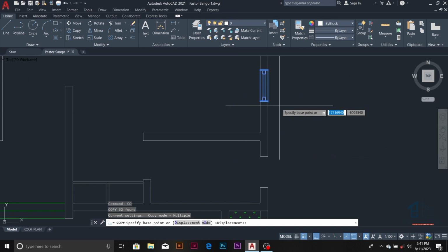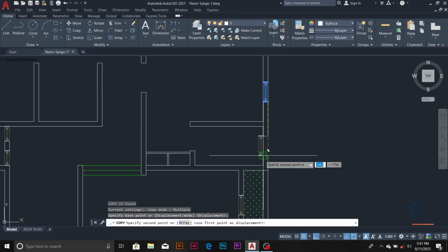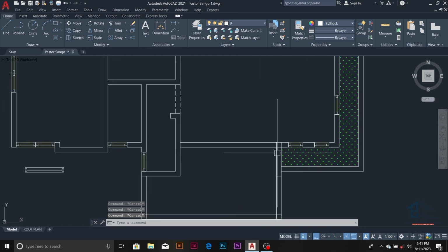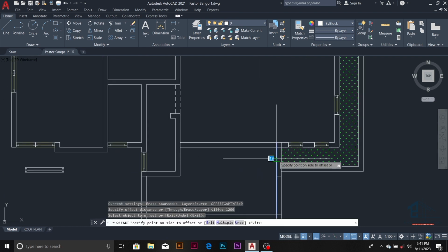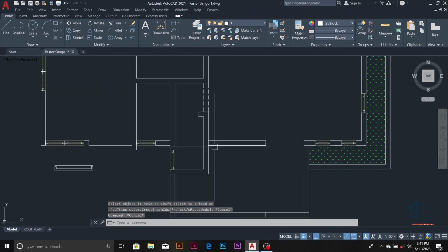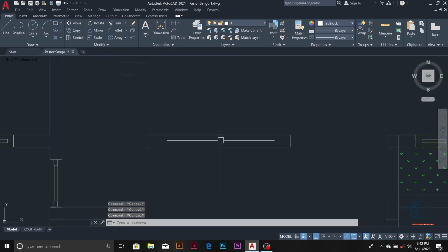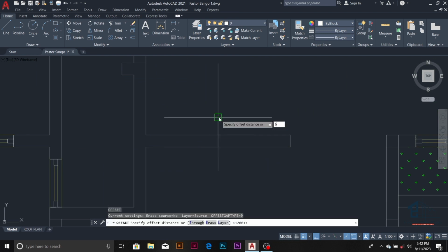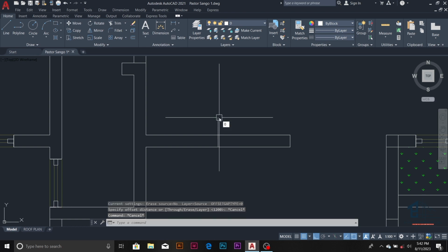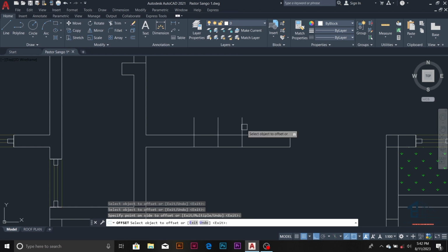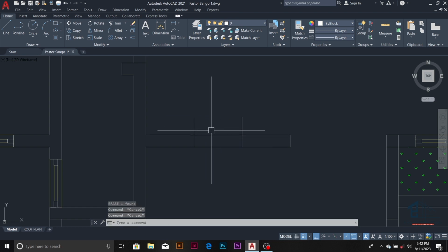So you will copy. So there's door here, offset 1.2, I'm using 1.2 door. Trim it here. Trim. And just put small door window here, offset 300. Trim it. CR.